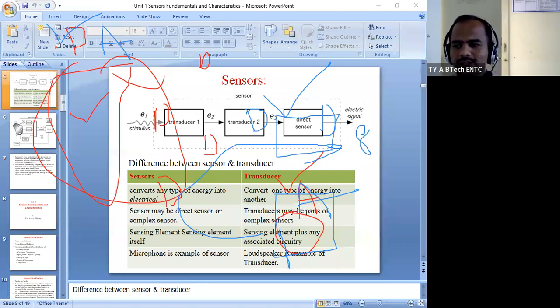Suppose we consider 8051. This is our controller. So whether 8051 is capable of measuring analog input directly? No, because an A to D circuit is not there in the architecture of 8051. For that purpose, we need to go with an additional A to D circuit or external interfacing of an A to D circuit. Are you getting? Okay.